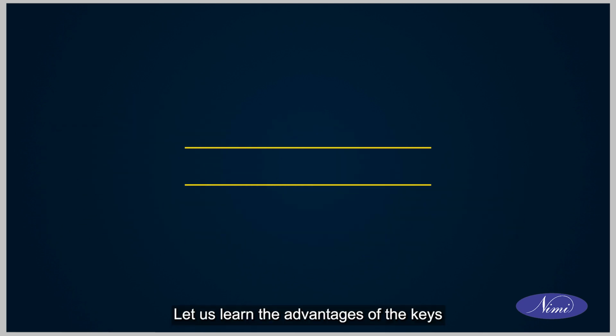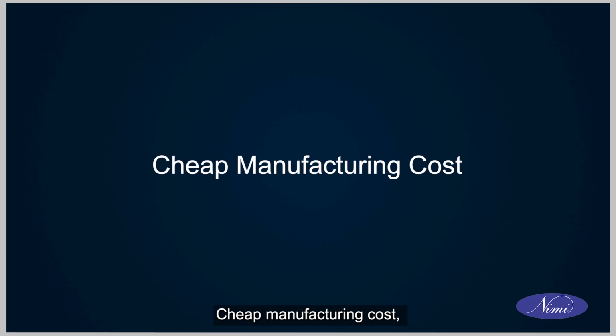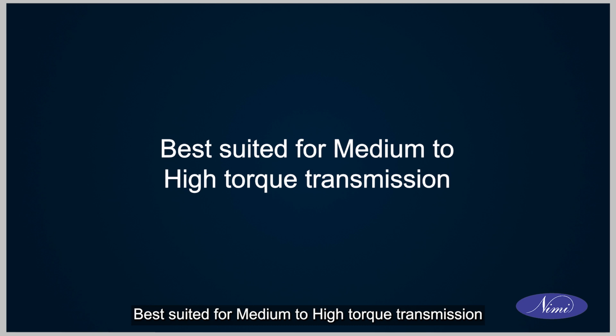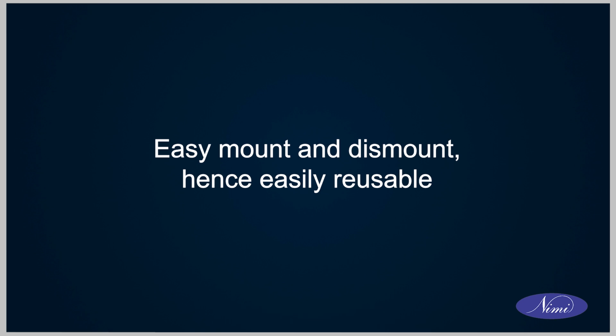Let us learn the advantages of the keys. Cheap manufacturing cost, standardized, best suited for medium to high torque transmission, easy mount and dismount, hence easily reusable.